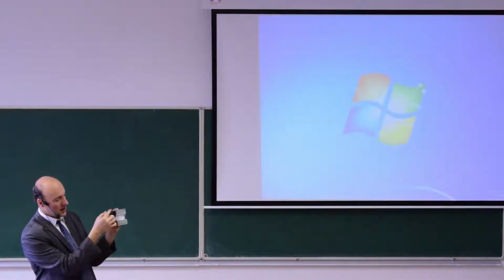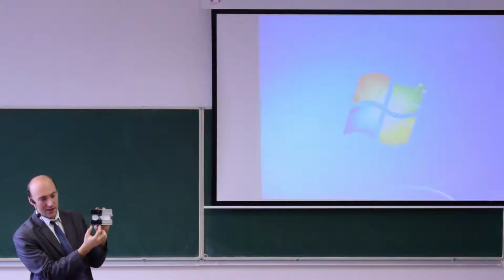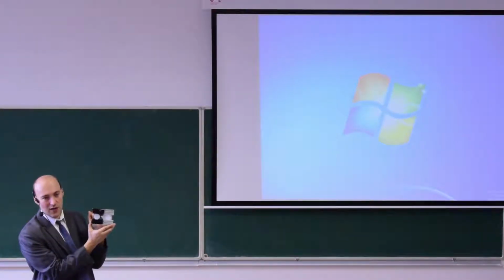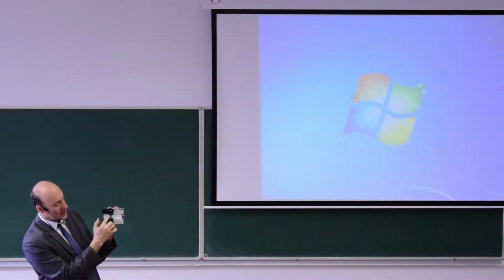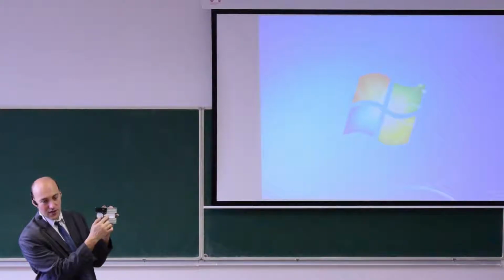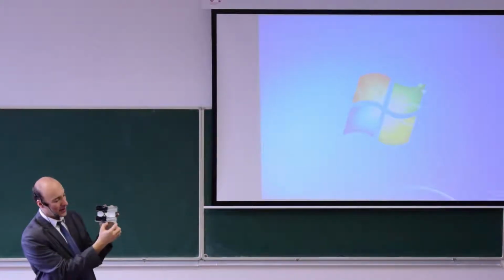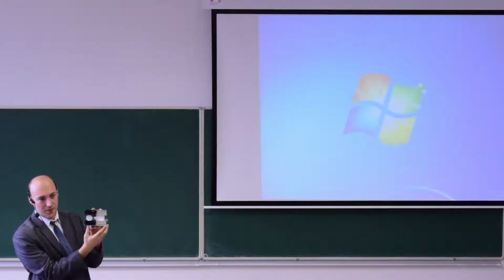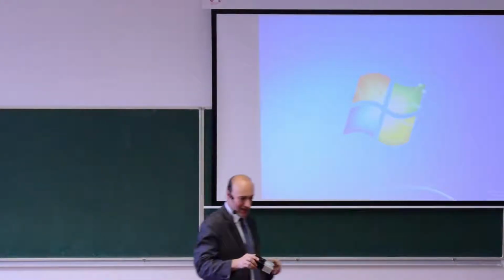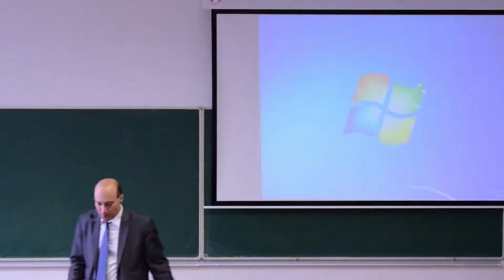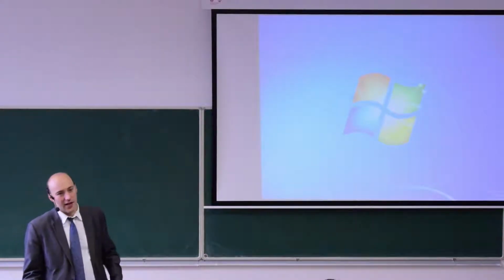So here the black part is painted with a color that has an emissivity of 0.96. You can see the stickers, so I can measure the temperature correctly on the stickers and on the painted area, but I cannot measure the temperature correctly on the original surface. So you can apply a special paint that works for temperatures up to roughly 800 centigrade.